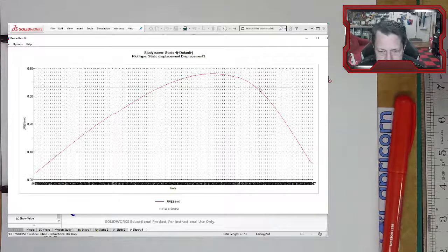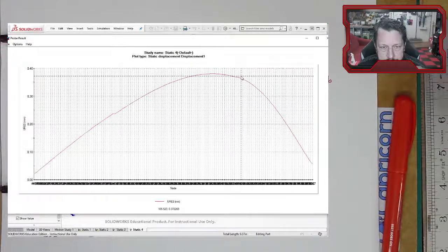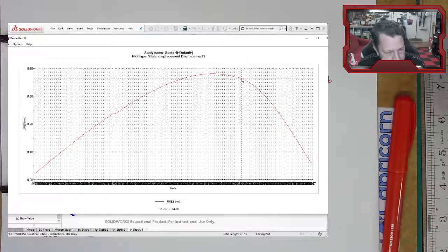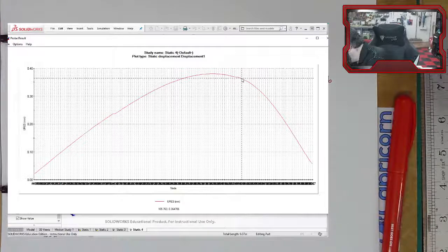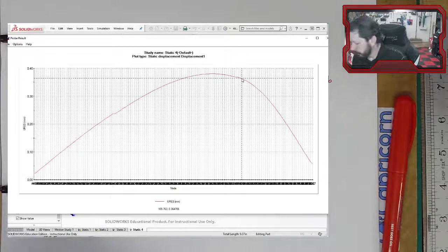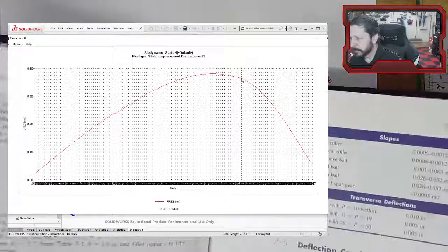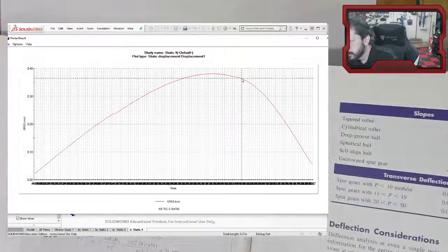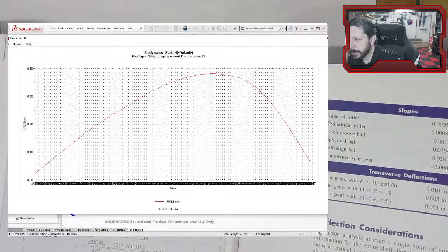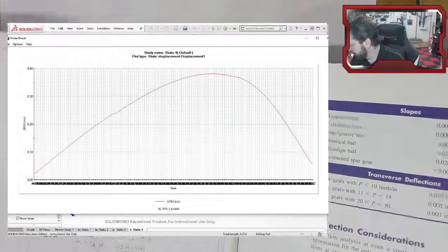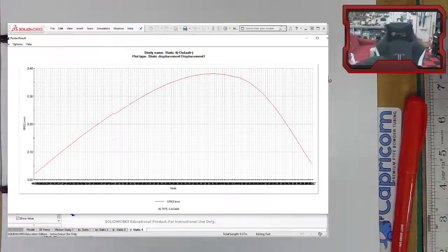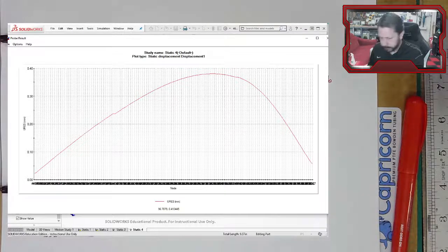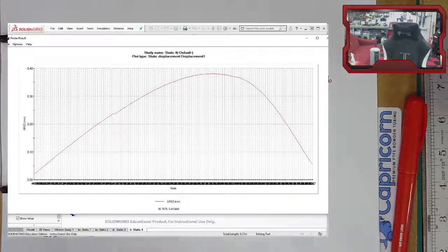Now at the gears, we'd have to have a marker where the gears were, but they're right in here. So at one gear, I am at 0.36 millimeters of deflection, and looking at my chart, whoops, dropped something over here. A little chart. Spur gears with teeth, a pitch of 16 can only have 0.05 inches of deflection, or else they've pulled the teeth too far apart. So 0.05, gotta find my calculator. Is that what fell? I don't think so. No. Where'd it go?